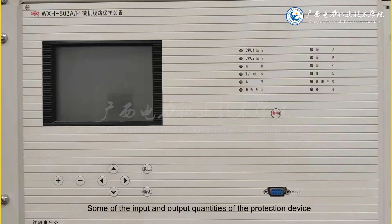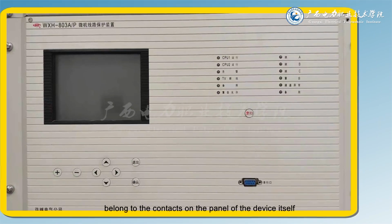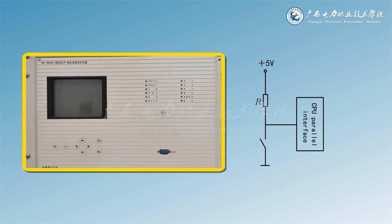Some of the input and output quantities of the protection device belong to the contacts on the panel of the device itself. The introduction path of these contacts is very short and there is no circuit connection with the outside. They can be directly connected to the parallel interface of the CPU, as shown in the figure.